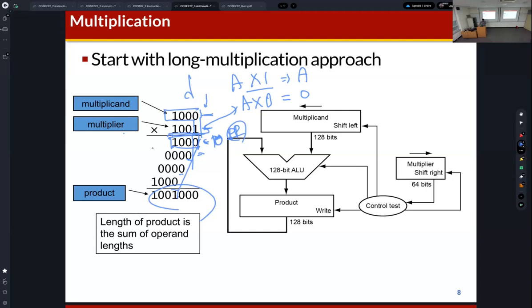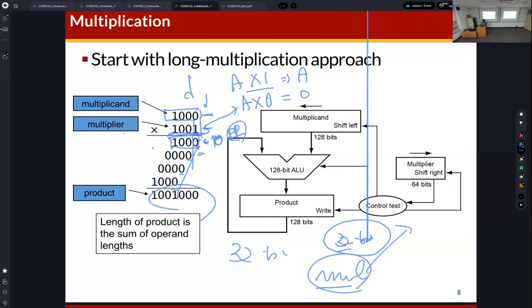So for the multiplication, we are learning about the 32-bit computer, which means the data size is 32 bits. If the mul instruction is given to a processor, we need to multiply RS1 and RS2, but these data are 32-bit data. So 32 partial products will be generated, and it requires 32 additions. We can use a reduction tree, but theoretically we can simply say a multiplier requires 32 adders.